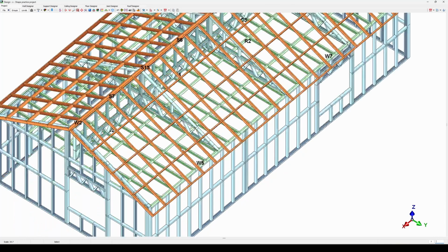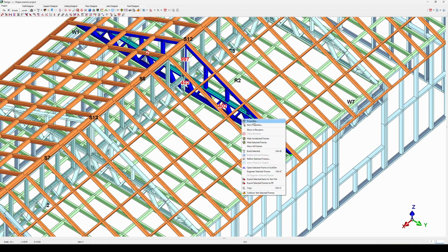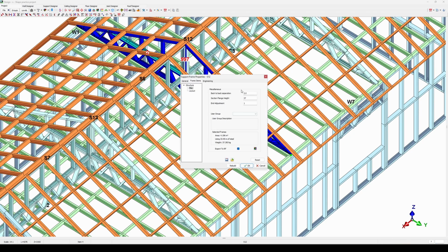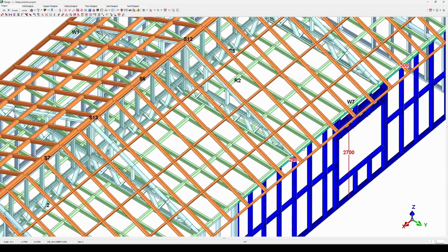Within the 3D Project tab, I'm going to adjust that support that I have created that cavity for by going to the Properties, right-click Properties. In the Generals tab, the minimum Z right there, I can place that on 2.7 meters. Hit the Rebuild button, and it places it right on top of my walls.